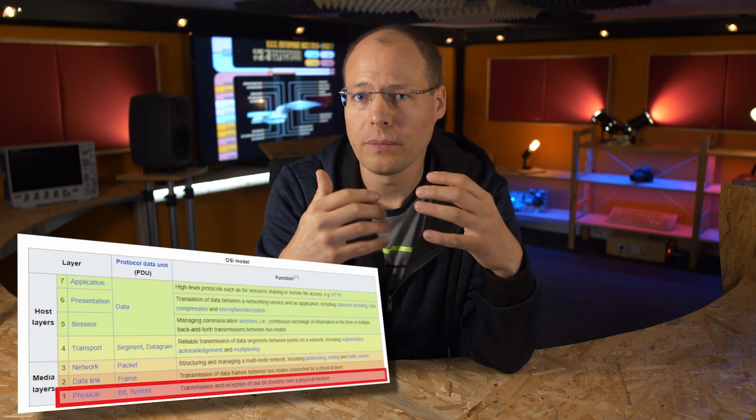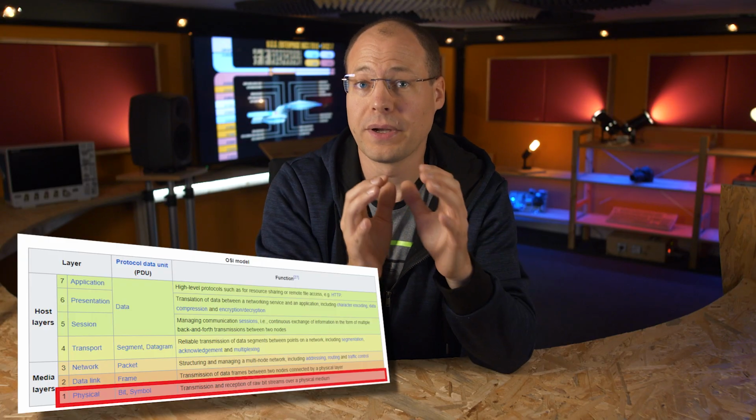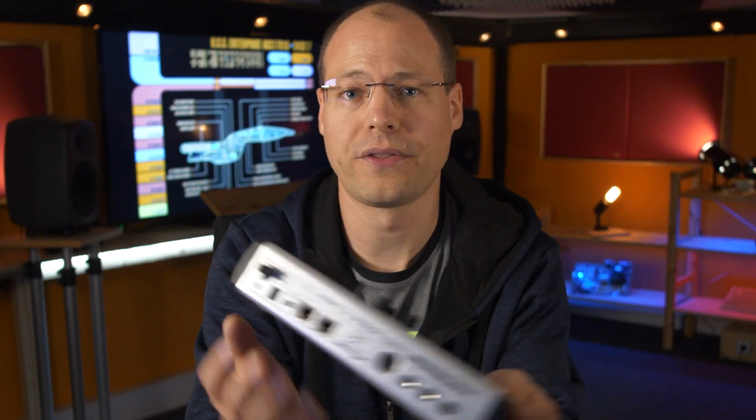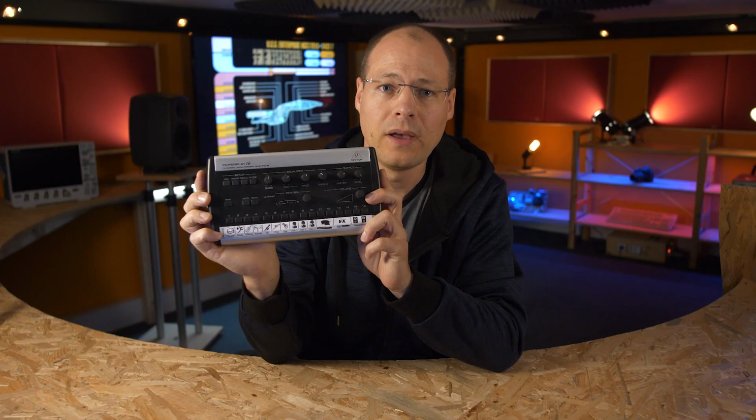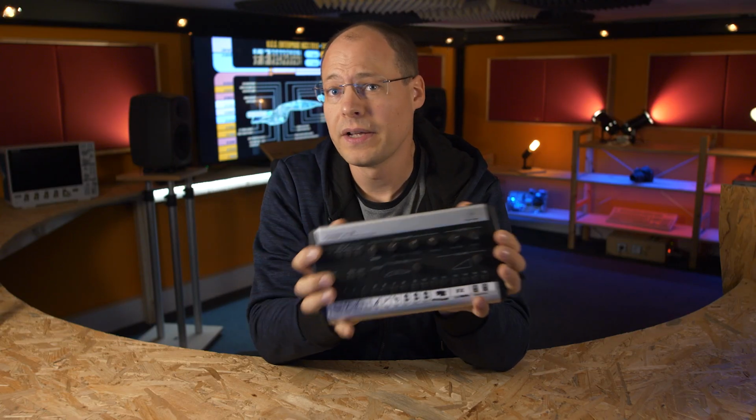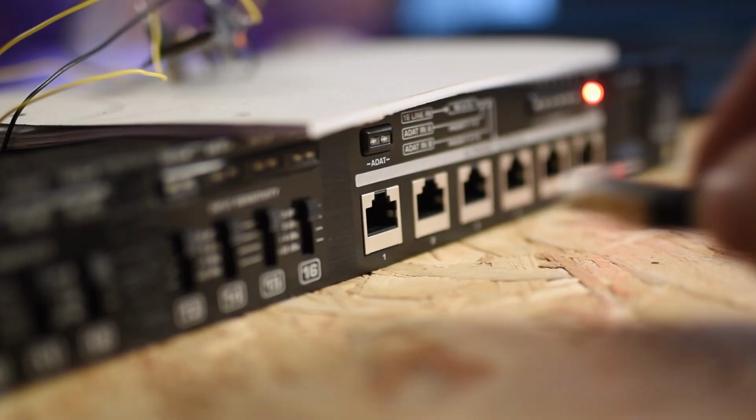The protocol used here is a proprietary 16-channel audio over Ethernet protocol called Ultranet, which is a layer 1 protocol because it uses Ethernet hardware but no Ethernet packets, which is good and bad. The good: we are not fighting against other network packets and the audio is always at top priority. The bad: we cannot decode the audio samples with a computer directly. If we connect some hardware that is actually intended for this purpose, like this P16M, we see that this piece of hardware does not work as expected.